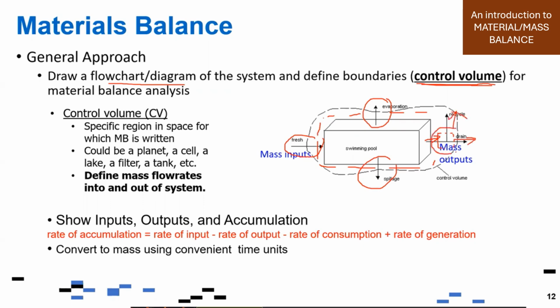So we are only referring to this part as the control volume, the juncture of your piping, all right? So this could also be a control volume if you want it that way. Finding the control volume is important so that you'll be able to identify the various components of the mass balance.